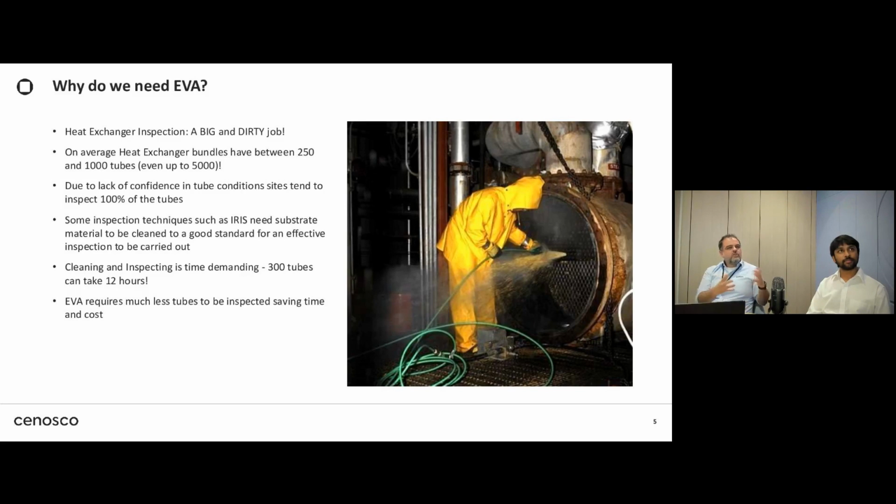and say, listen, we used to use as a reference for estimates 300 tubes a day using IRIS, right? So 300 tubes in 12 hours, of course, be a little bit more or less, but that can give an idea on how much time is needed to do that task. So you can spend basically a crew of 2-3 inspectors on the bundle for 12 hours.